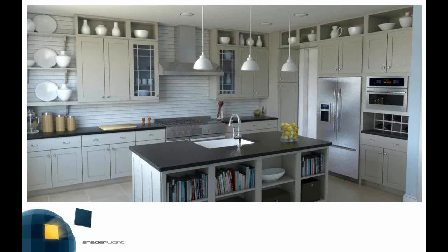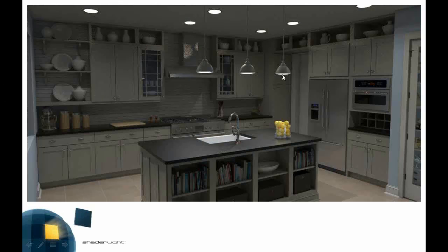Right. Well, really the major difference between an exterior render and an interior render is global illumination. This will mean the light will actually bounce around inside of the scene. So when you're putting lights inside a room, it will bounce off walls, whereas externally, that's not where it's coming from. Ultimately, lighting an external scene, we've done a webinar on this in the past, and as I mentioned, it's well worth having a look on YouTube. If you set a dark IBL, which can just be a dark JPEG, then it's lit very much the same, just using those different lights. So for a nighttime one here, we've just got these artificial lights, and the global illumination is then bouncing around the room.